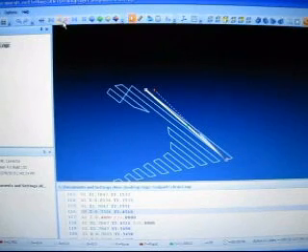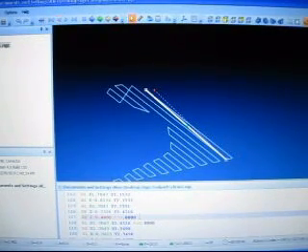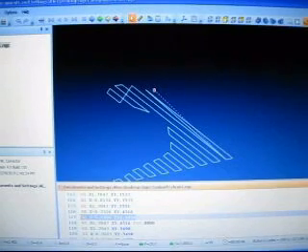So, stepping through this thing, okay, we want it just before this line, okay? But what we have just before that line is a plunge. Okay, you can see that it's a G1, so it's feed, but the feed rate is different. It's a plunge feed rate. I set it to 20.